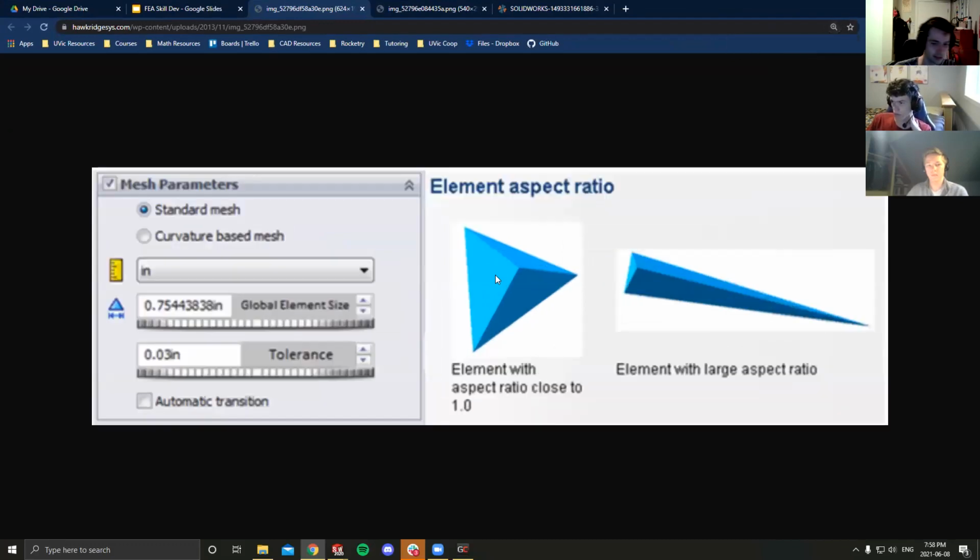These are tetrahedrons, or a D4, if you're familiar with tabletop RPGs. The tetrahedrons are selected in such a way to minimize the interior angles on that tetrahedron, keeping all of the elements as close to an aspect ratio of 1.